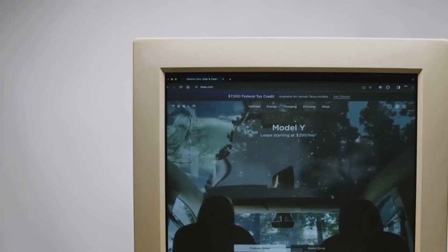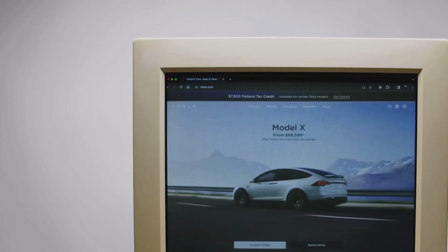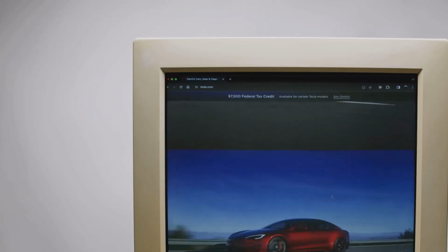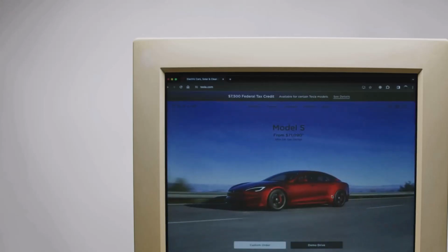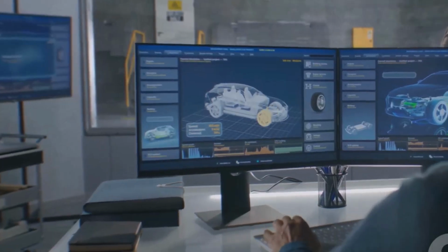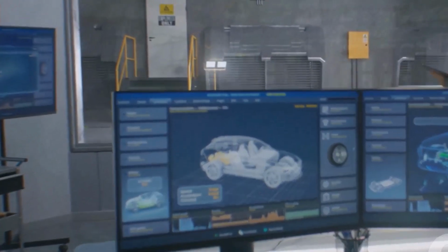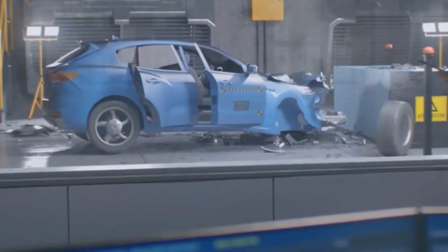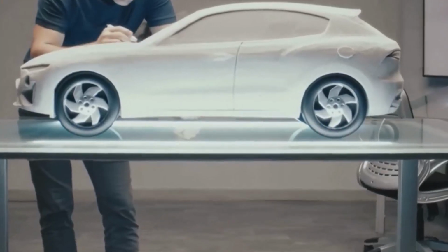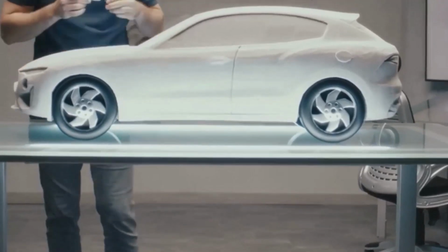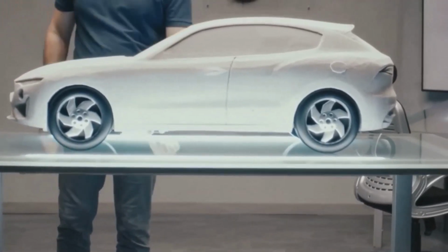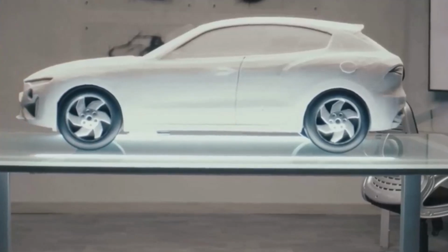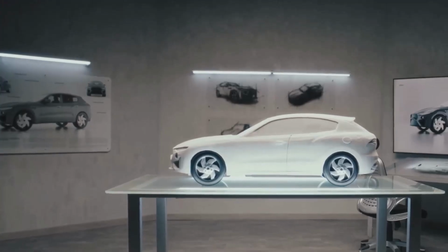This skin friction drag is determined by the wall shear stress, which is exactly what we need a low Y+ to predict accurately. By creating a simulation with a Y+ value of 1, engineers can precisely calculate the drag on every curve and panel of the car. This allows them to make tiny adjustments to the car's shape, maybe changing the angle of a side mirror or the curve of the roof that can reduce drag by a few precious percentages.